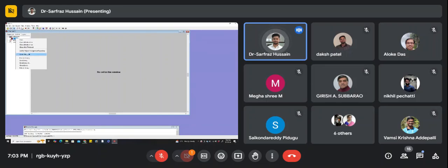Now once I create this library, I need to have some cell. What cells will I require? First let me create an inverter cell. I'm not going for any AND gate or NAND gate, but simply I'll create an inverter cell. For that, just right click, or you can go to cell and new cell, or otherwise just right click and click on create new cell.